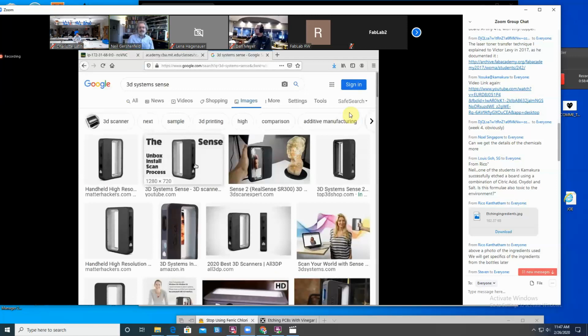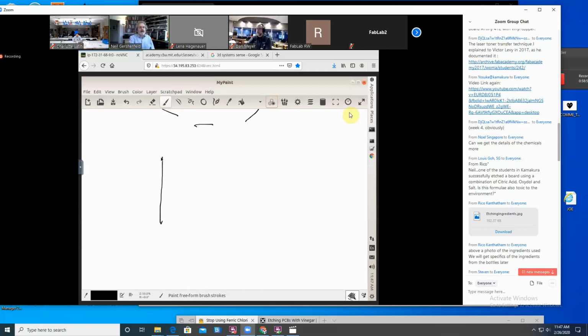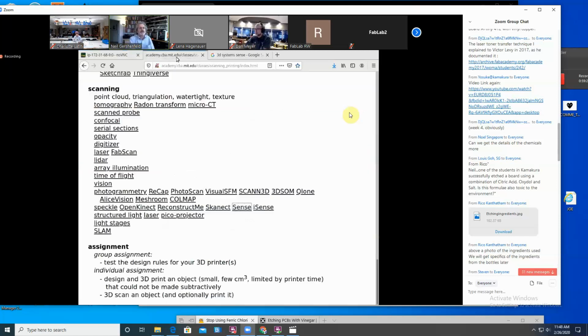And what it's doing is it's different than the laser scanner. The emitter is putting out a speckle pattern. The speckle pattern is like random dots. And then the camera is looking at the speckle pattern. And so you do photogrammetry. As you move it, it's taking pictures. But the difference here is at the same time it's taking the pictures, it knows about the speckle pattern going out to illuminate it. So it's taking pictures of the object with the speckle it's putting on it. And that gives it much more mathematical information to do the reconstruction.